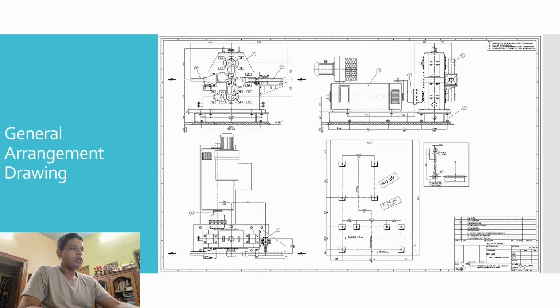Here you are seeing a drawing sheet showing a particular machinery. I have put this here just to show a very basic general arrangement drawing. Let me first discuss what this is. This is a crop and cobble shear, usually used in rolling mill applications, and it is a dividing type crop and cobble shear.